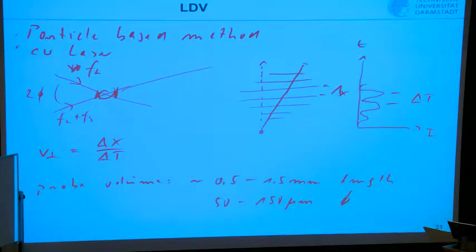And if you have a higher experimental effort, you can do LDV with 2 setups and then measure the correlation between adjacent points. And then deduce integral length scales, and in principle you can deduce from that by Fourier transform a power spectral density in the wave number regime.